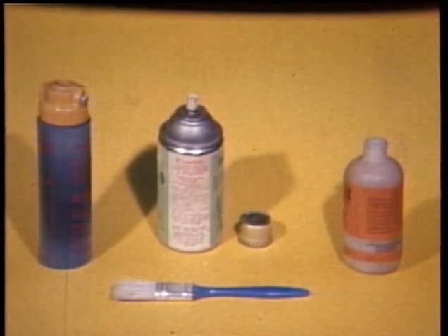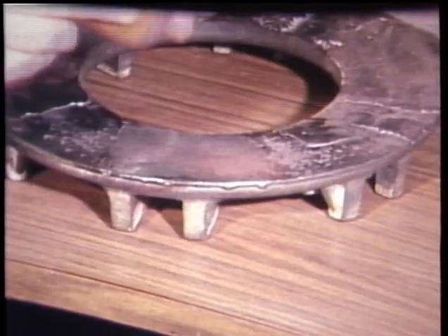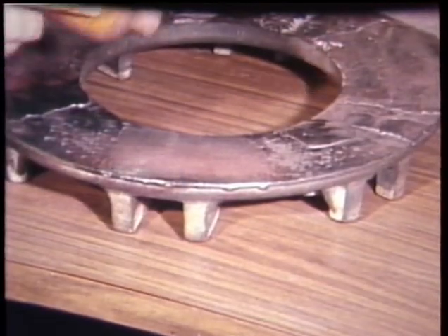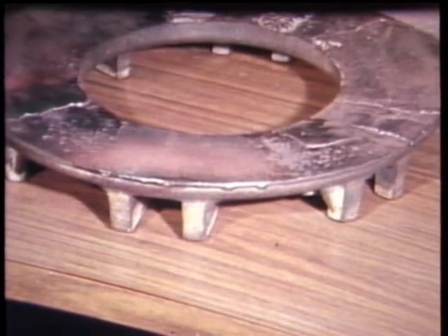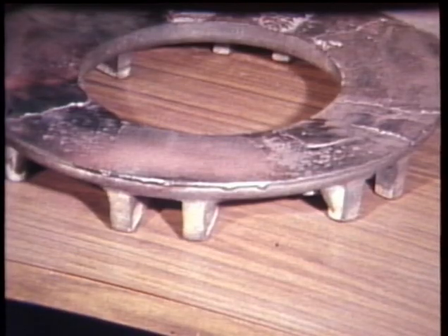Magnetic particles can be applied using a dust bag, atomizer, spray gun, brush, and so on, depending on the type of particles used, either a wet solution or a dry powder. If a dry powder is used, it should be applied evenly over the test area. Excess concentrations of particles should be removed in order to accurately inspect the surface.